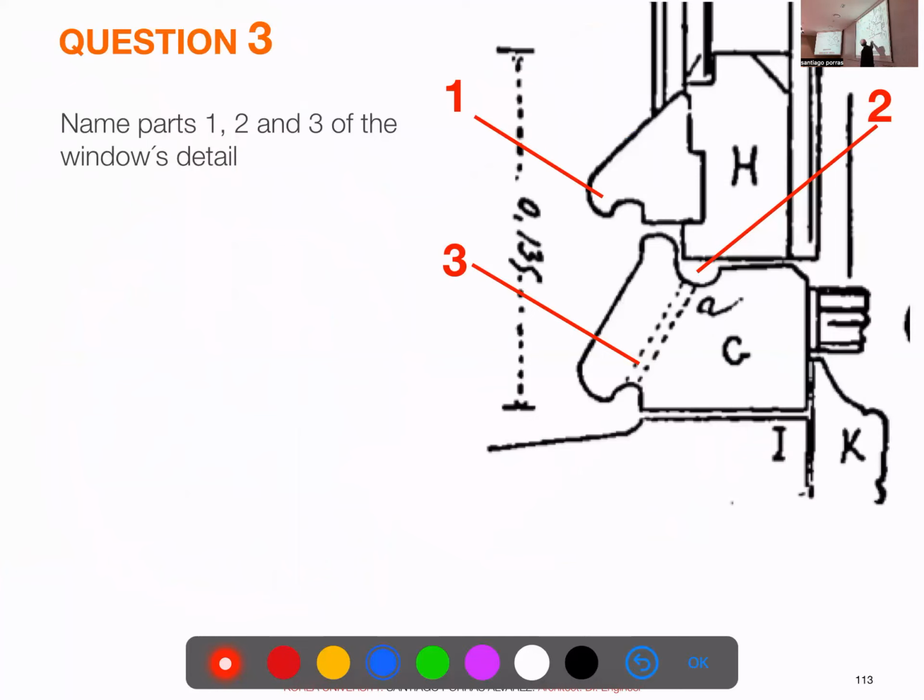So now we have this small window frame. Remember, this is the seal, which will continue until the dripper. This is a stone, right? We have the frame, we have the sash, we have the trim, and there's like three elements I notated, which I invite you to identify, to remember their names and say what they are. Because this is a possible exam question. We can have any other window, and you have to identify or analyze what you see there. And I think it should be easy. If you did the window assignment, you came to class and you understood it.